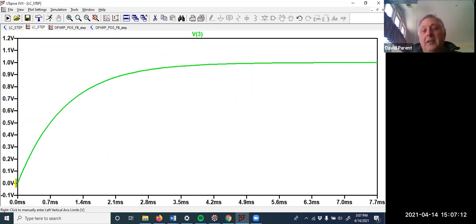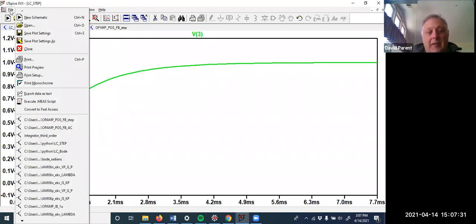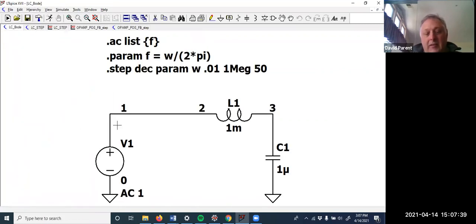Because what can happen is when a system has two real poles and it's very overdamped, one pole is a lot faster than the other. And so it decays so quickly that you don't even notice it. And so it almost looks like a first order system. And of course, the only way to tell really is the Bode plot.